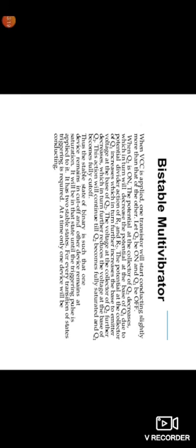Here is an important point we will remember: for every transition of states, triggering is required. Whenever the external pulse is applied across the base of the transistor, that transistor will go into the saturation region and the other transistor will go into the cutoff state.